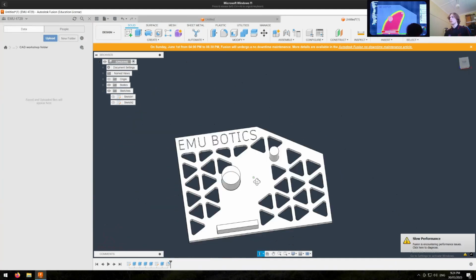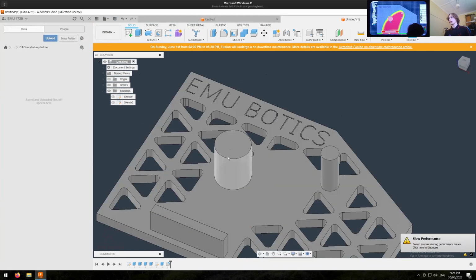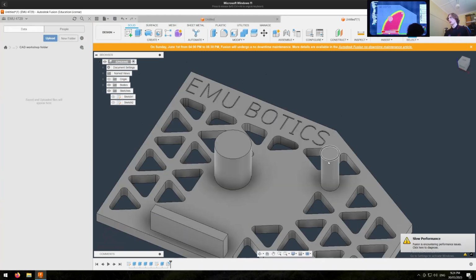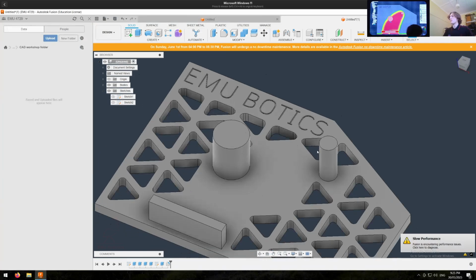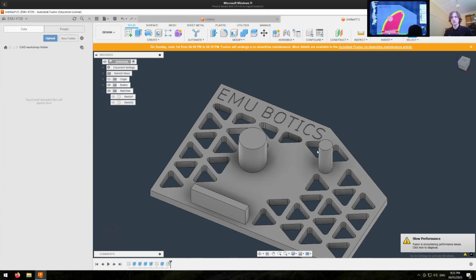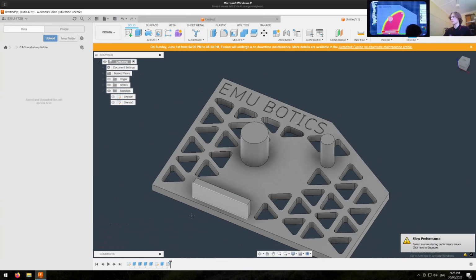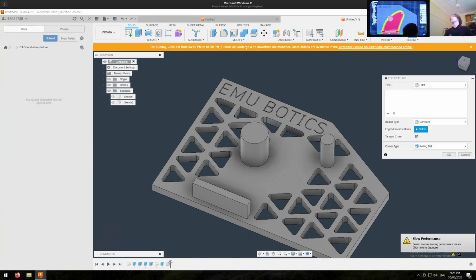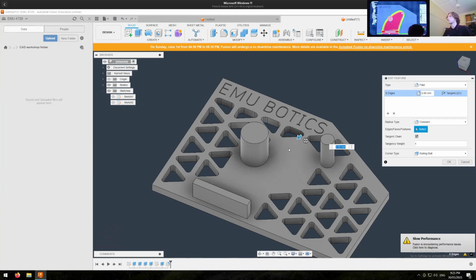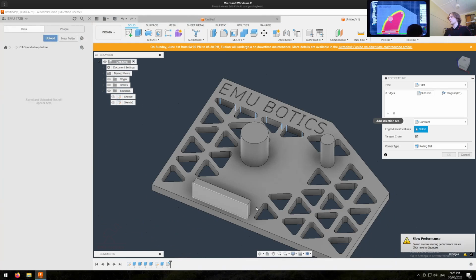And cool. So there are some other fillets we might want to add, like this would be a little bit sharp. Obviously, if we're CNC machining something, we need to be very careful with the fillet tool because it can be very expensive very fast. But otherwise, if we're just 3D printing, don't need to care about it. Fillets everywhere. Fillets are fun, fillets are happy, fillets are friendly. Everybody loves fillets. And so I'm going to add just some extra ones on here.